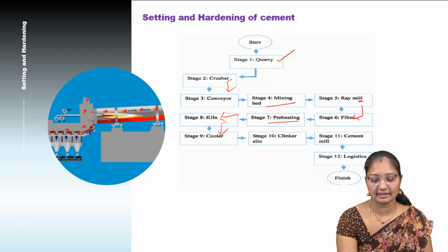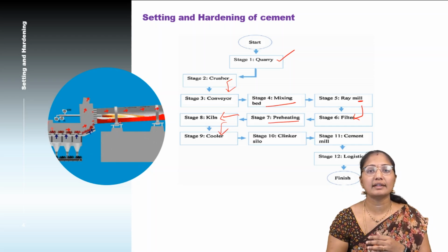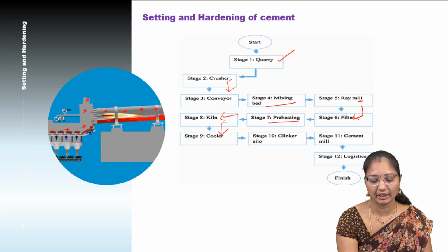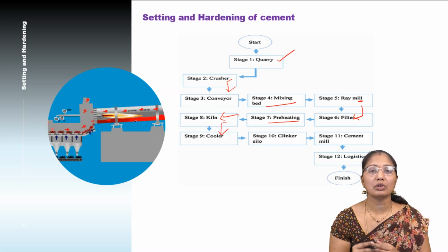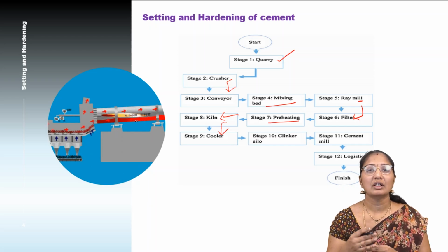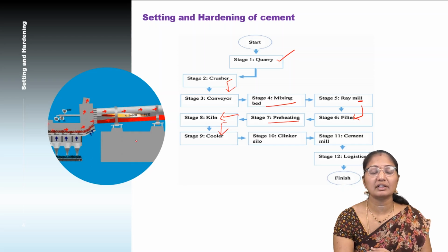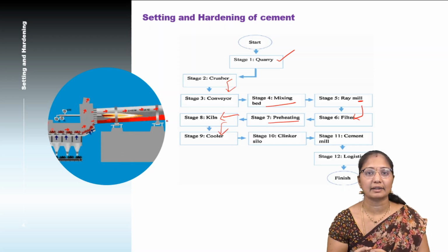Here we can see this is the sintering process. Through the conveyor belts, the homogeneous mixture enters the kiln. This is a rotary kiln, so it rotates and heats the homogeneous mixture this way. Here all the carbon dioxide or impurities present in the cement mixture get evaporated. The mixture present in this kiln is called clinker. So we will call it the clinker.